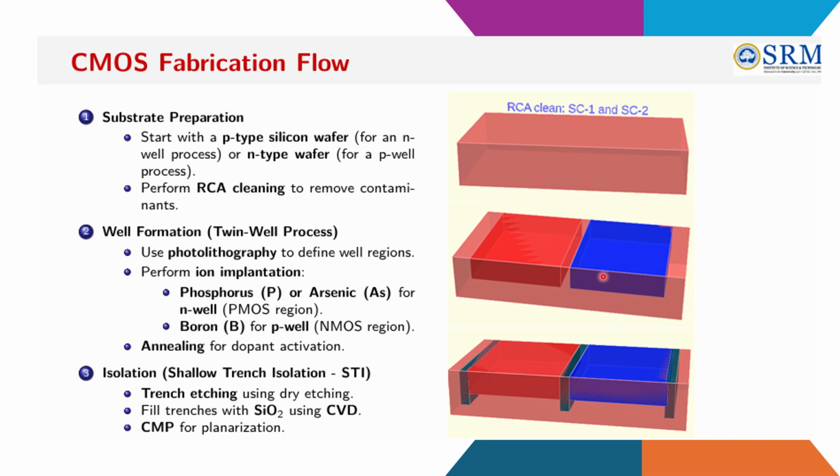But if there are some variations in the dopant, then to repair your device, you can use the annealing process. Annealing is the repair. If you want to repair the dopant, that is, make it uniform, because there may be non-uniform placement of your p-type and n-type because of some voids, or because of multiple regions in your crystal, how will you repair the crystal?